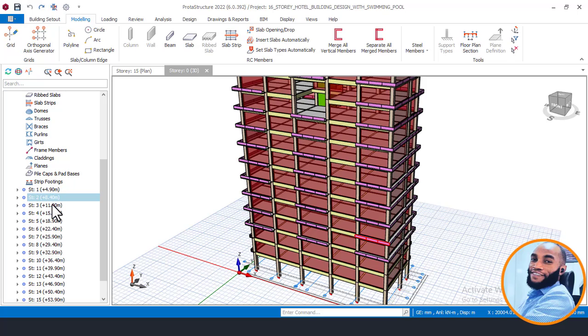Okay, so basically right now we are going to begin to apply our live load reduction when it comes to waffle slab from the 3rd story, because the 3rd story is giving us 11.9 meters. Can you see that? So right now we are going to apply that from the 3rd floor, which is basically this.